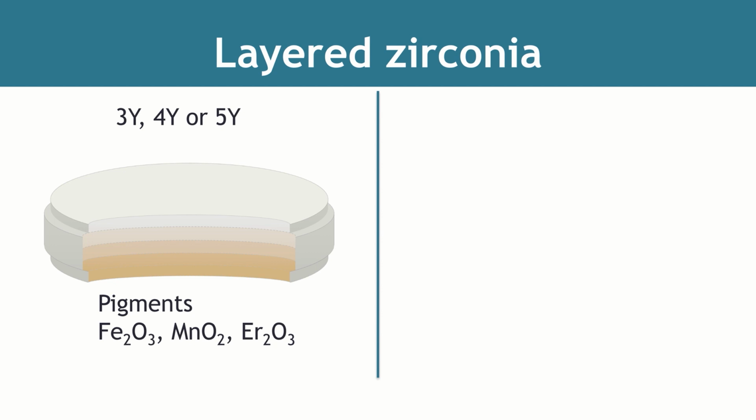These can be divided into two main types, color graded and strength graded. In color graded, here shown to the left, the zirconia blank shows a gradient in color from the addition of varying amounts of pigments. The aim of the design is to mimic the natural color gradient found in teeth, so that the resulting dental restoration is most opaque in the gingival region and gets increasingly lighter and more translucent towards the incisal area. In this case, the amount of yttria is constant throughout the material.